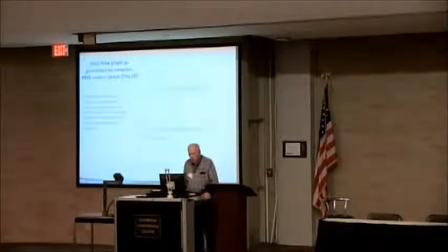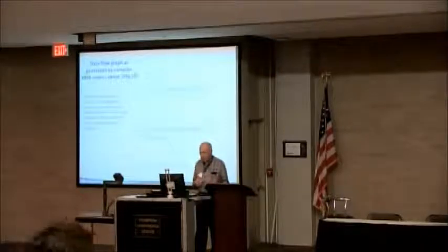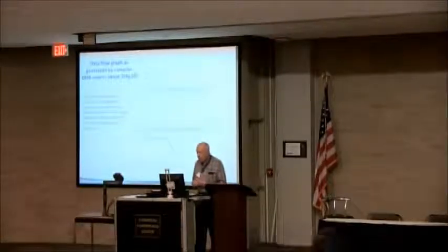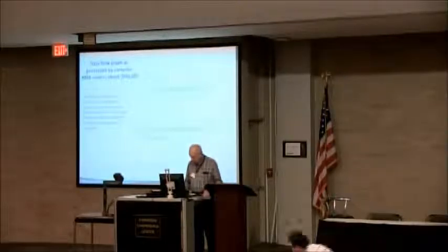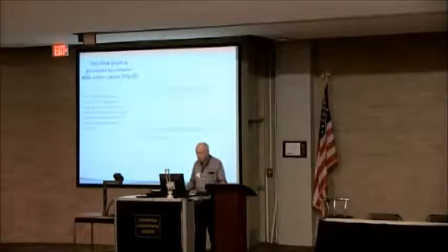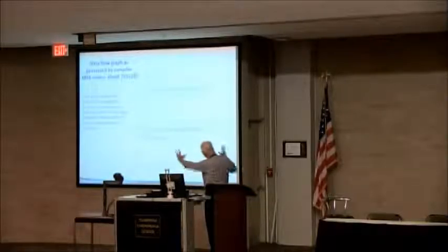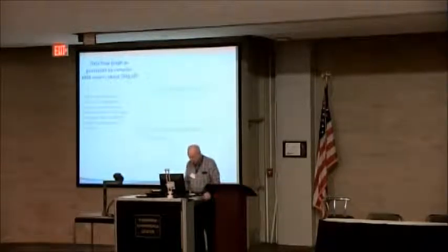So it looks at all the operations and reconsiders the parallelism available, the algorithm that's being used, and the data structures, and then changes the aspect ratio. This is now showing all of the parallelism that's available in the program at this point, but it won't fit exactly this way on an FPGA, so you have to modify it to make it fit.